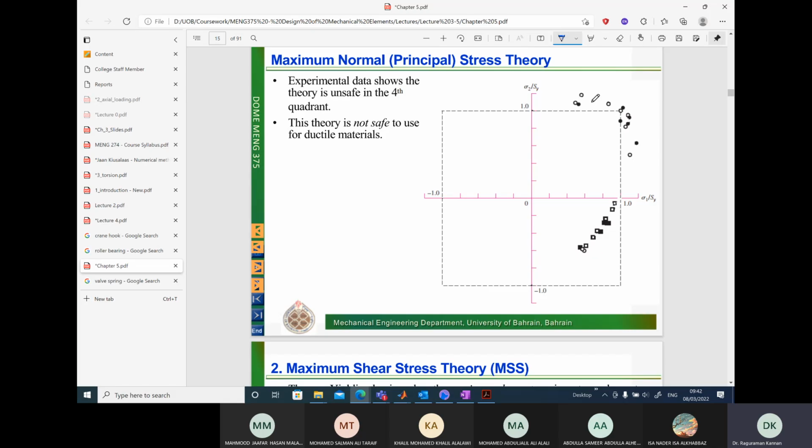Okay, we apply tensile loads, and based upon the tensile loads, remember this, in reality we are dealing with 3D specimens. Although we apply tensile loads in a particular direction, maybe we have failure here in one direction. If we apply only a tensile load as a 1D problem, we are going to get sigma 1 value here, somewhere near this guy, an experimental data.